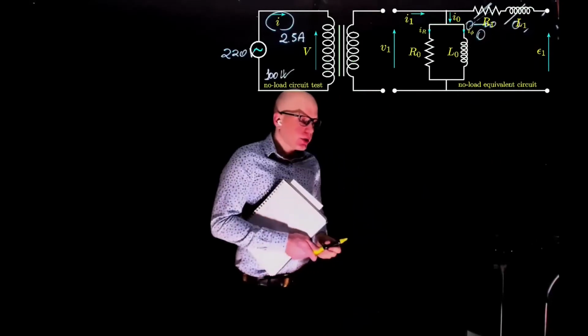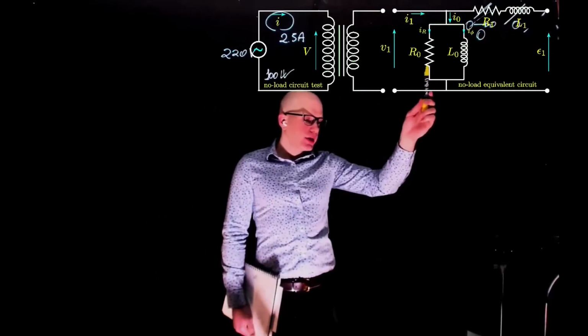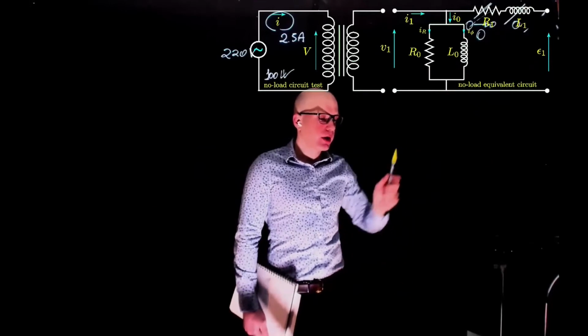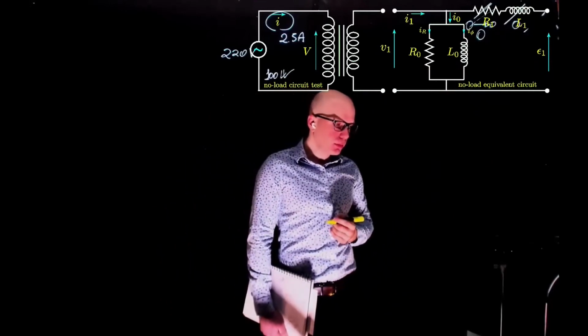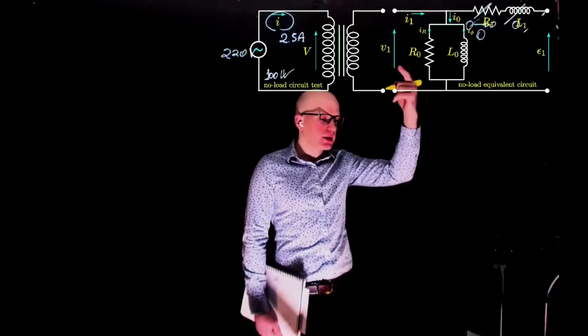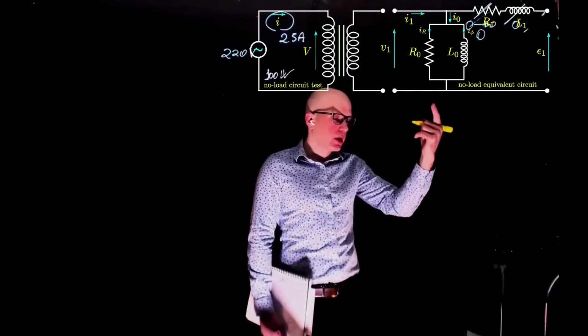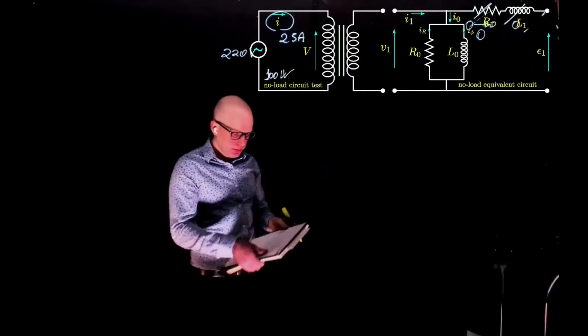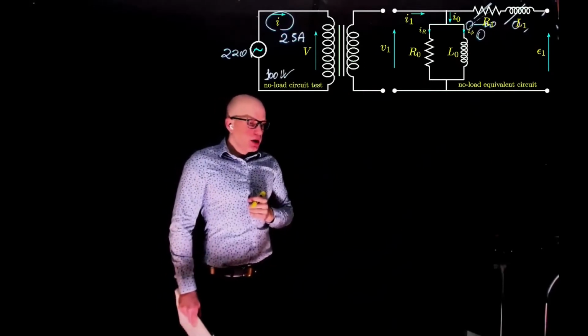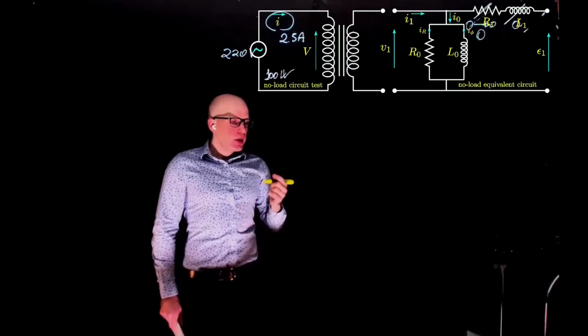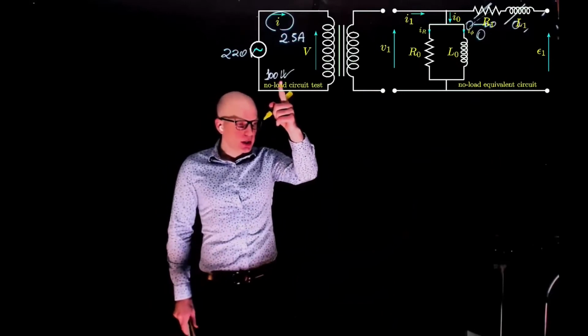The question we are trying to answer now is, what is the value of this R0? What is the value of that L or the reactance X0? And what is this magnetizing current, and what is the current dissipated in joule losses? This is easy to do, knowing that it takes 100 watts at the input.